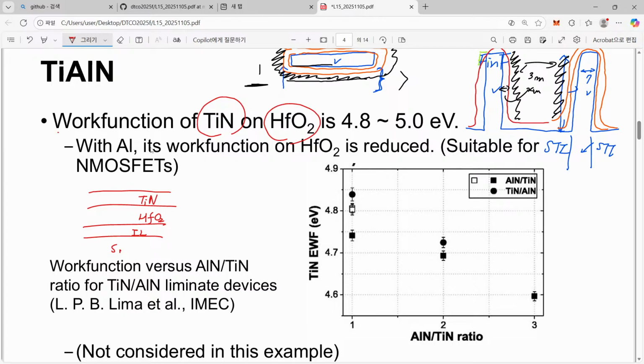If we measure the work function of this titanium nitride layer, I wanted to give you the concrete number. However, from experiments, depending on process conditions and composition, they show a certain range. Just to understand, these are the known ranges of titanium nitride on hafnium oxide, and this value is not suitable for our N MOSFET, but perfect for our P MOSFET.